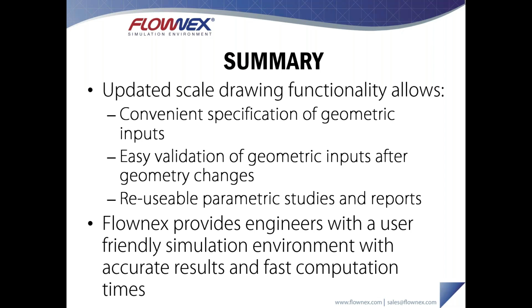Lastly, it also makes it possible for us to reuse our parametric studies. So in the first iteration, I set up a parametric study and was able to reuse the same parametric study in the second iteration. Often, if you would have quite a large change in the geometry of your system, it might almost be more convenient to insert the components again from scratch to ensure that you don't forget to change an input. But by linking the inputs directly to geometry, you can be confident that all the inputs will be changed, and then you can safely reuse models.